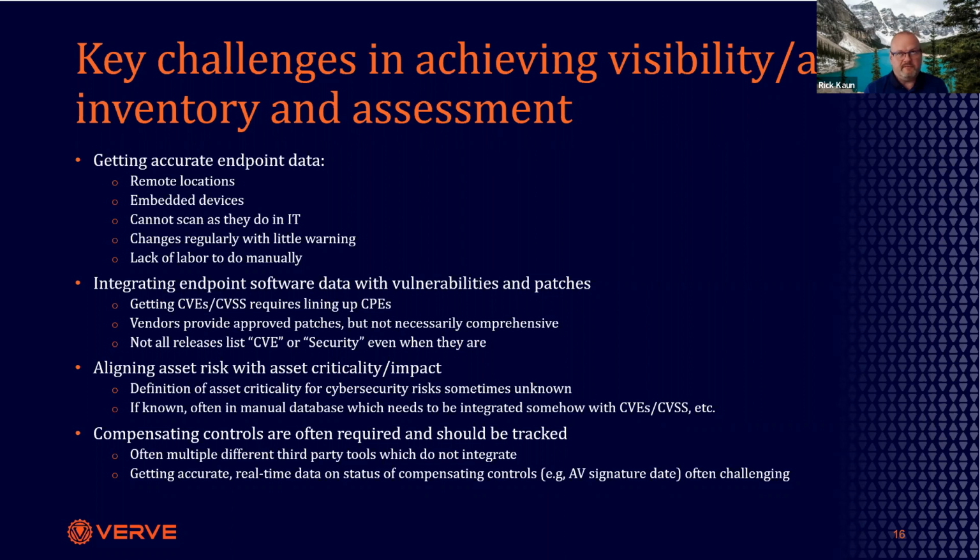vendors still carry a fairly outsized stick, I think. They want you to only apply patches that they've approved. But the problem is they only test patches that affect their software. And if you run a Windows OS, you have vulnerabilities outside of what the vendor has approved. Quick example. Did one of these deployments, we pulled up the patch dashboard, we showed 1,200 missing patches on average on Siemens systems. And I'm not picking on Siemens, it just happened to be Siemens for this one. It's the same for Emerson and Honeywell, et cetera.